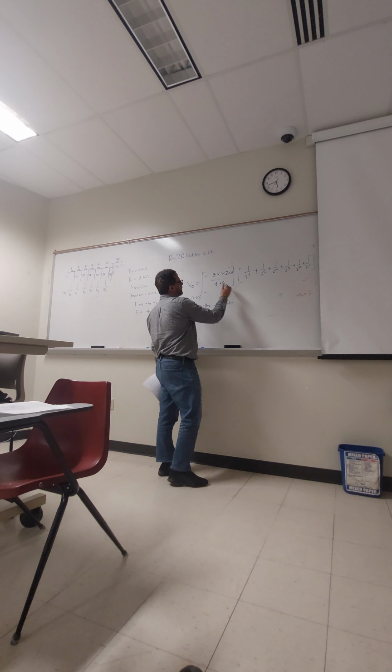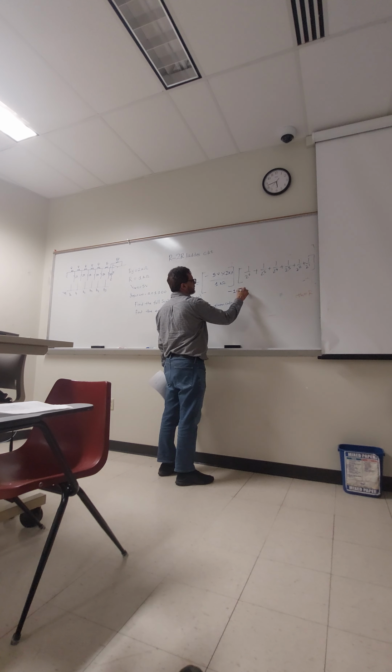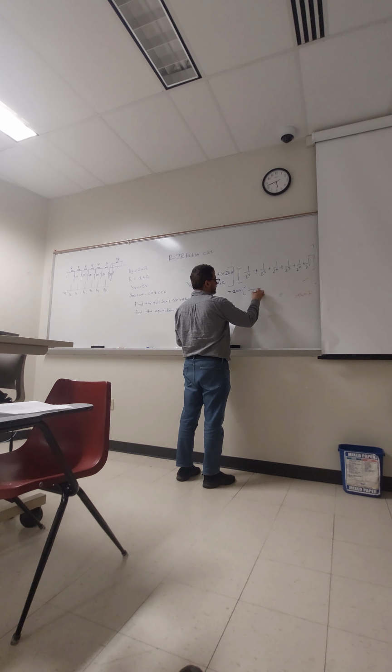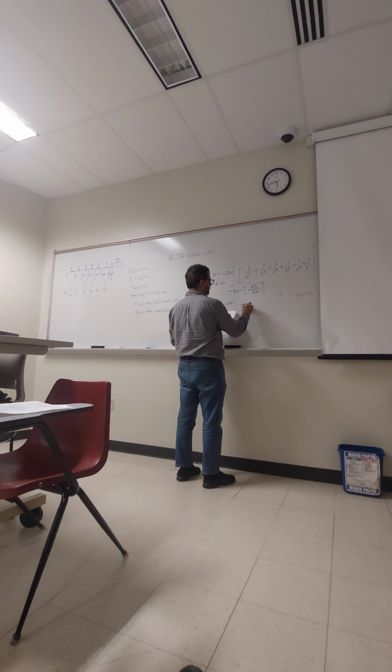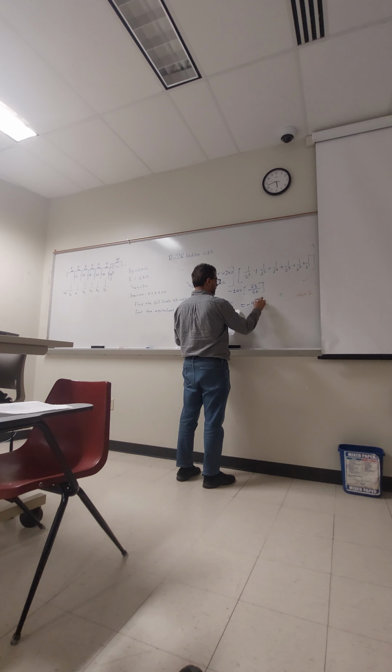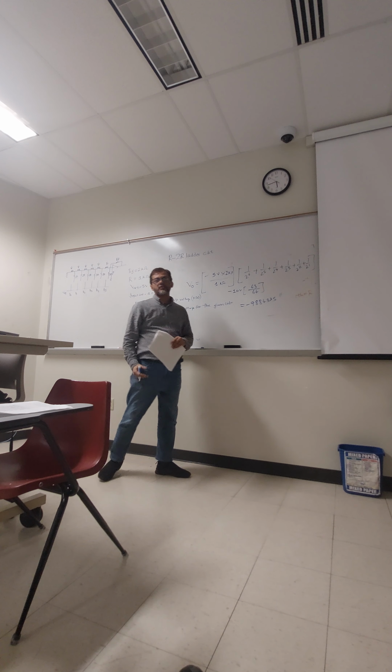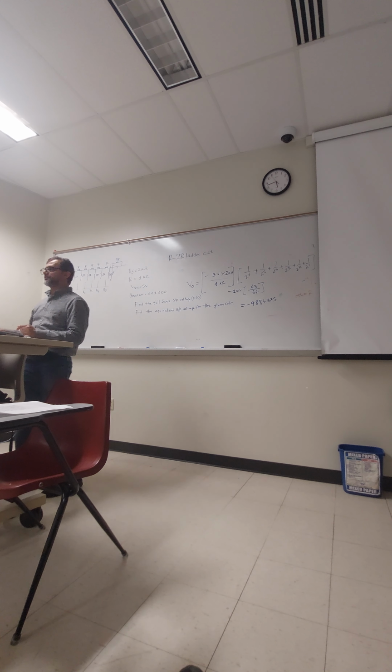So here it will be minus 10 volt times 63 over 64. Then it will give you minus 9.884375. This is the full scale output voltage.